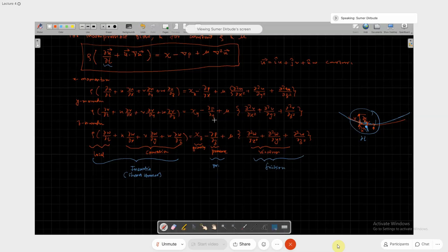And pressure is the pressure you are feeling inside that domain along that axis. And here, whatever you see, these are viscous terms. Okay, viscous terms, and these are also viscous diffusion terms. Okay. So in this case, we have seen that momentum is transferred through these velocities. Now here there is no bulk motion. You can say that convection is a bulk motion. Through this bulk motion, the momentum is transferred from this location to this location, or this location to this location. Okay. Because of that bulk motion.